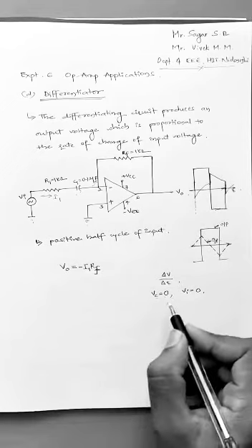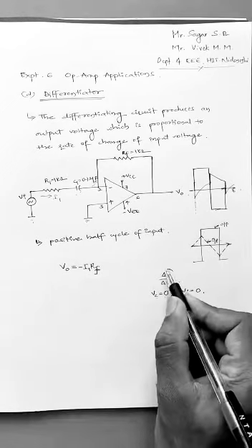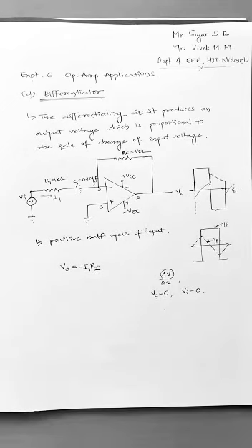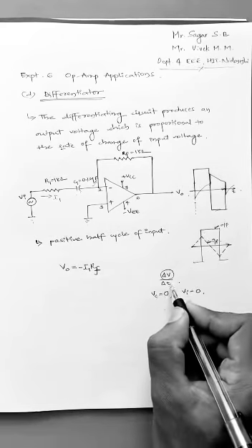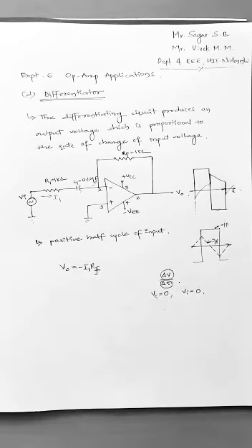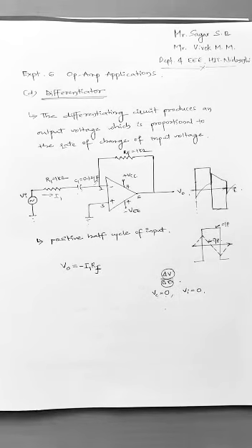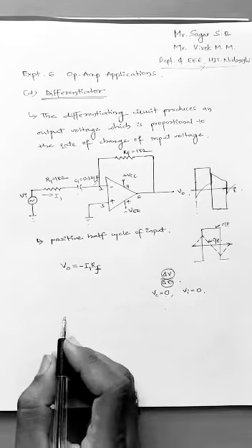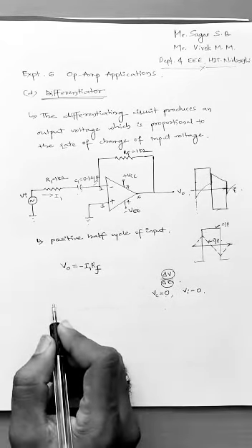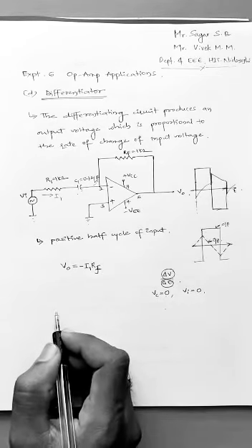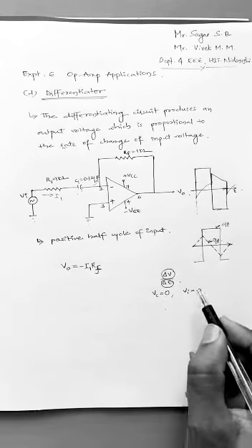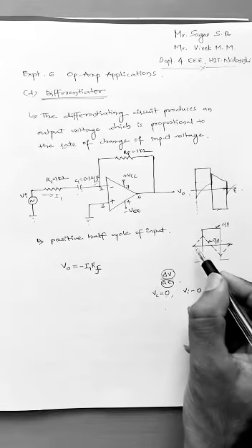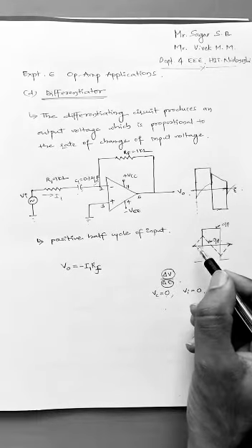So that change of voltage stored on the capacitor, I will note as del V. And the time to change the voltage over the capacitor is nothing but the small change in time, that is del T. During this time, say the capacitor charging current is constant as the rate of change of the input voltage remains constant. It is a linear waveform, so the change is constant.